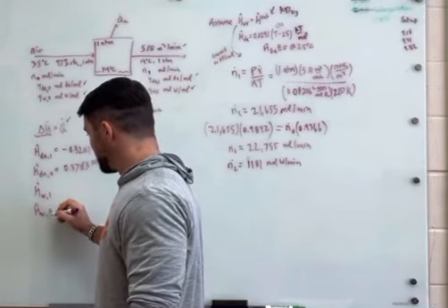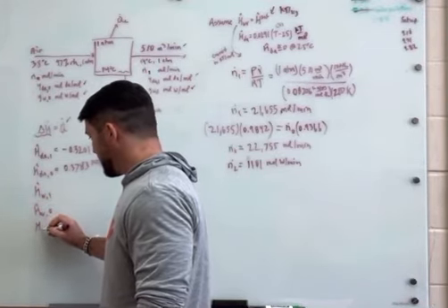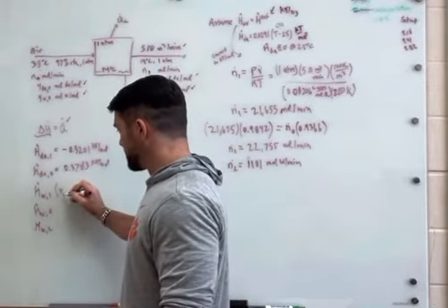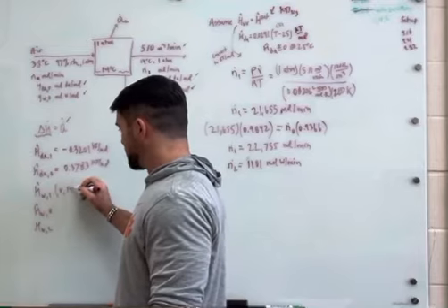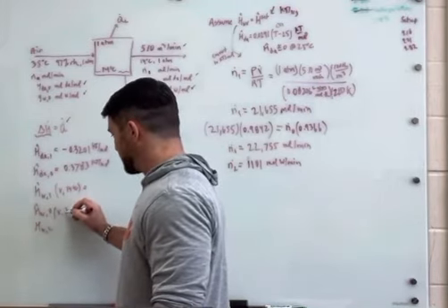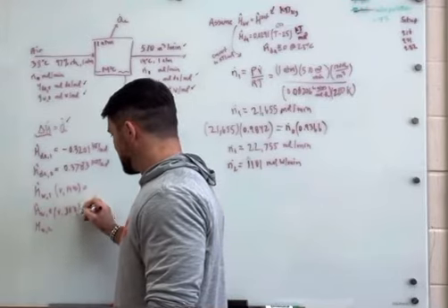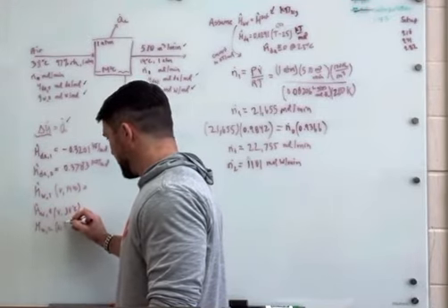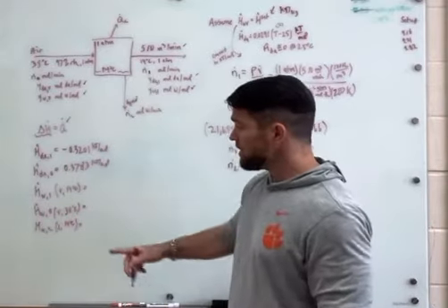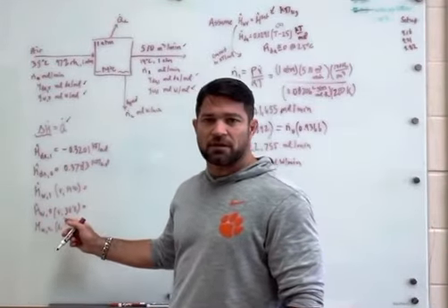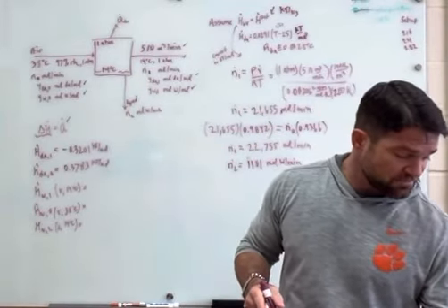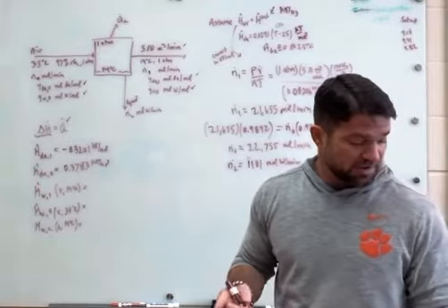in the vapor entering, and then we need the enthalpy of the water in stream 2. Okay, so in this case right here, this is going to be a vapor at 14 degrees C. Entering is a vapor at 38 degrees C, and then this is going to be a liquid at 14 degrees C. All right, so I'm going to get all these values from the tables. So we're assuming it's a saturated vapor, so we can go to table B5.